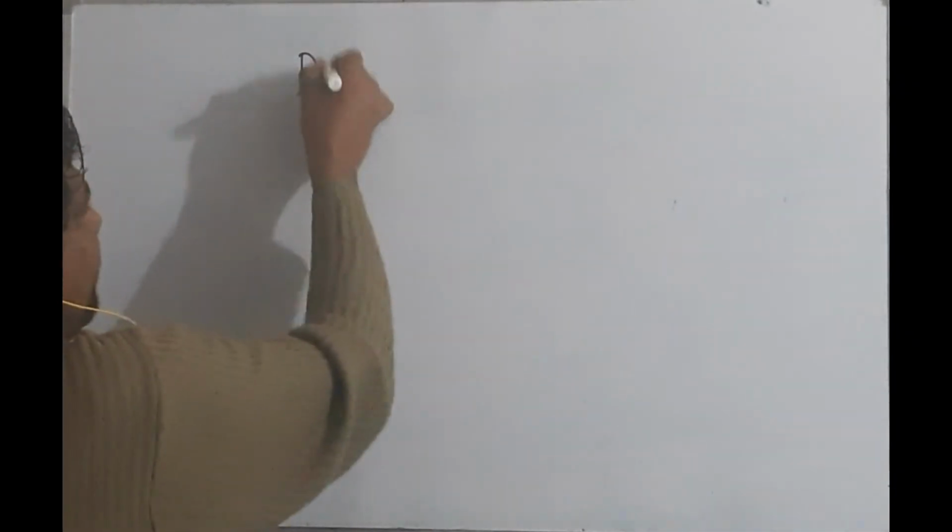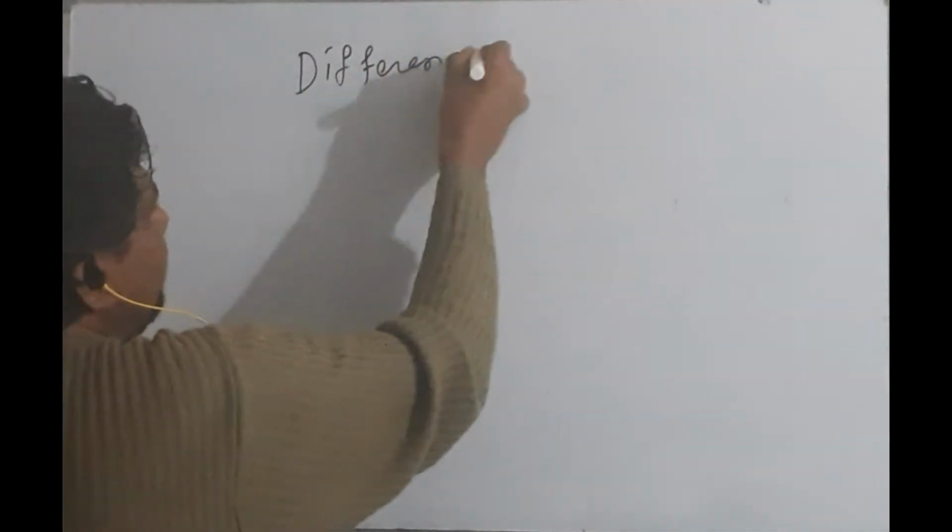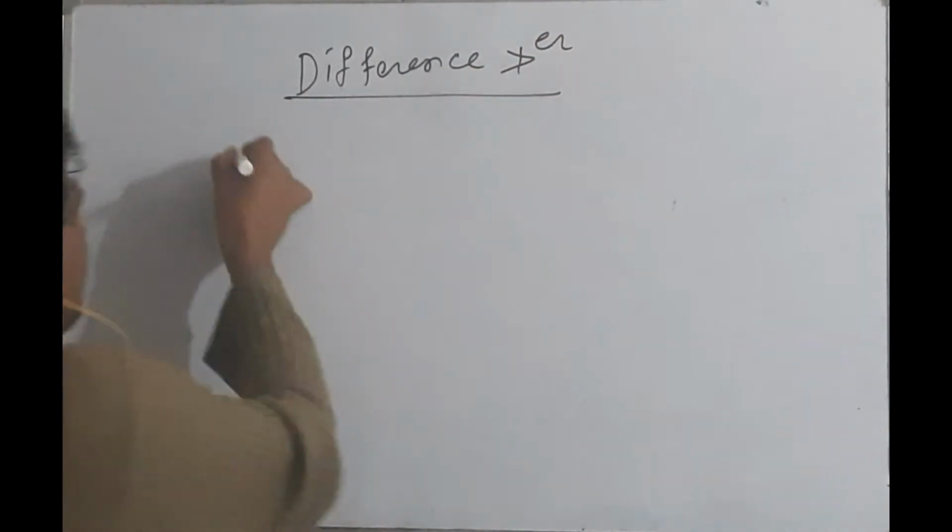Now most of the time we need to find the potential difference between two applied voltages. So let us think about the difference amplifier. I have a difference amplifier, negative, positive. I will use values RF, R1, this is Vx, this is RF, V0, R1, this is Vy. So I should get Vx minus Vy as the output difference.